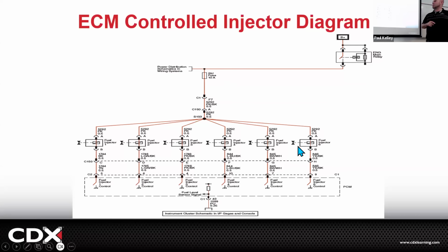Because I know if it was that fuse, none of them would start. If it's a misfire in cylinder 3, I'm really going to start my diagnosis maybe just down here, after that splice S103. All right, so you can visualize that. It's not that complicated, I think.